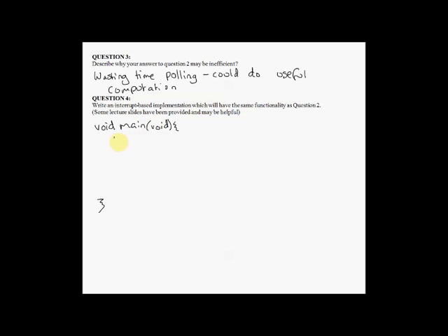So we want to set up pin 5 as an input, so that was basically our first line of code. P1DIR is equal to 0xDF as before. We want to enable interrupts for pin 5 then, so we're unmasking that one. P1IE equals bit 5.